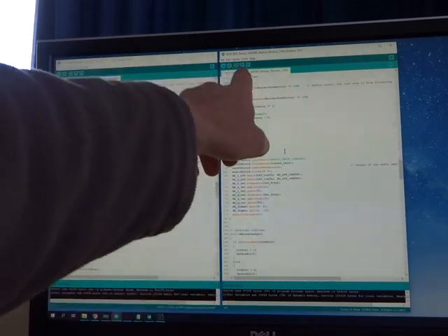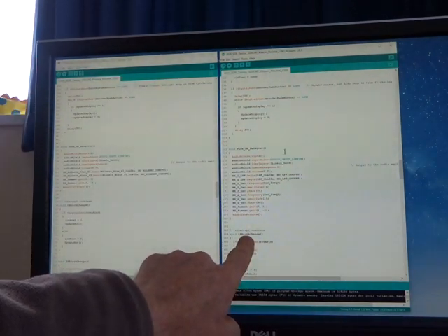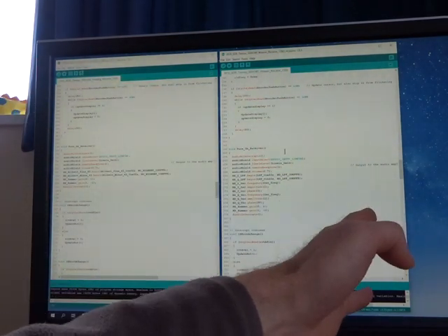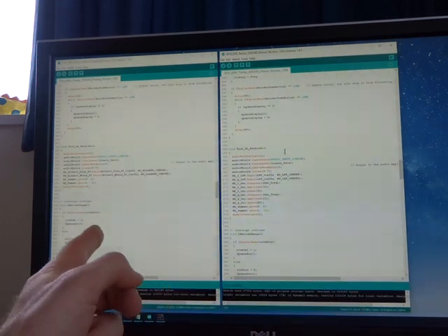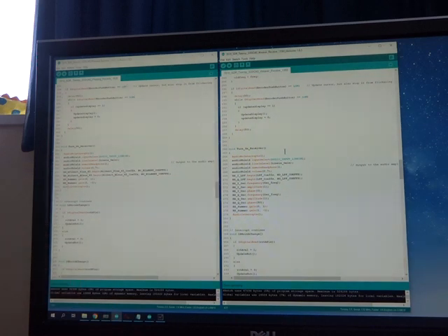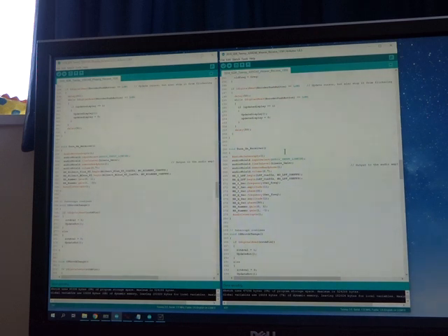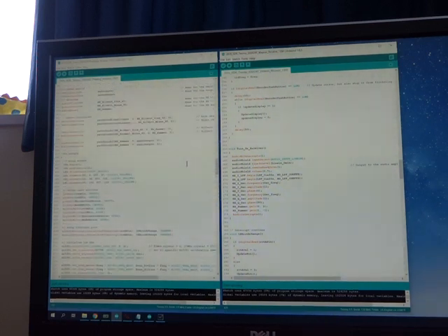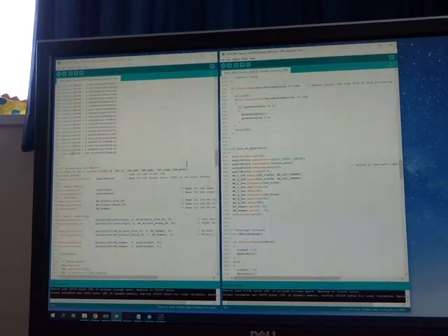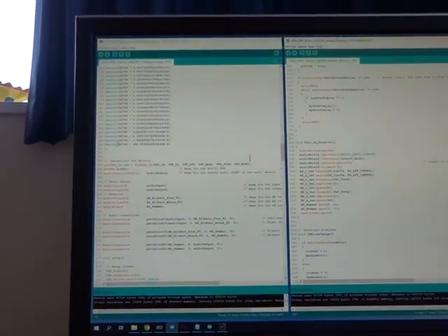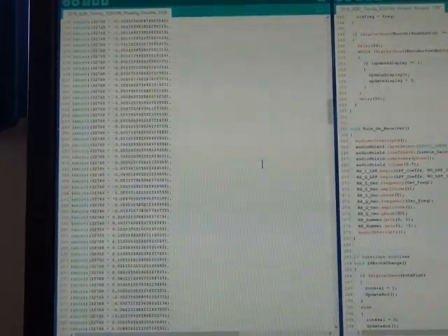For now I'll park the Weaver as an interesting exercise, put that to one side and continue working on the phasing receiver, and basically convert it over to a transmitter. Then I can always double back around and look to better optimize the coefficients and the levels coming in to better suppress the unwanted sideband. But it's very easy to vary the inputs there, which is good.